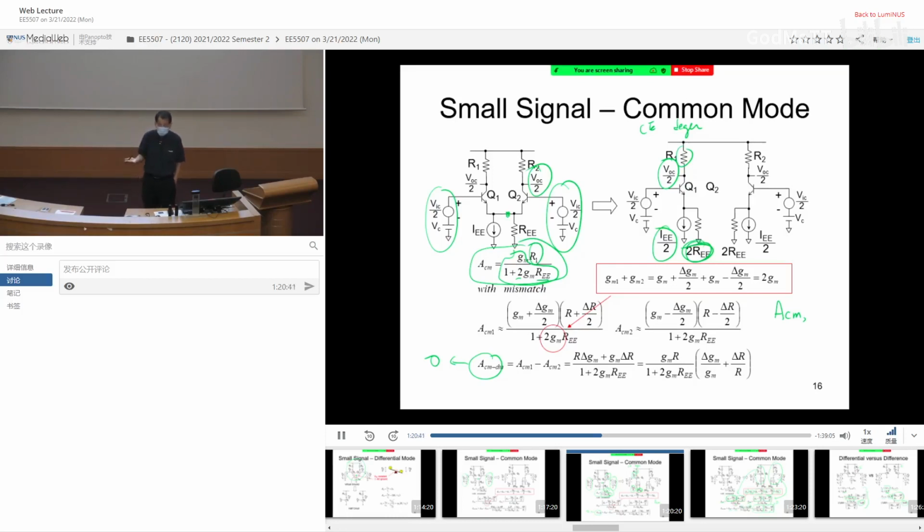How about normal noise? Now, if you think about normal input noise, you also have this kind of characteristic, because let's consider here, right? These two persons, very close. The noise source is from the acorn over there. When they have the close proximity, the noise source from there reaching both of them should be quite identical, right? So the circuit is the same thing. A lot of time, a common noise source, when they appear to these two differential inputs, they appear to be the same.